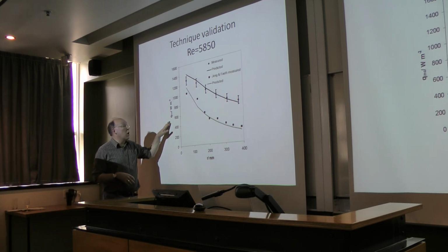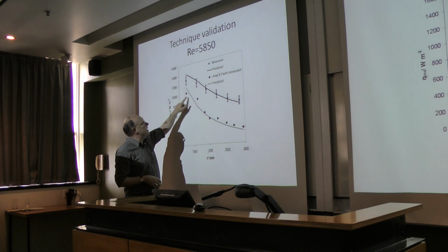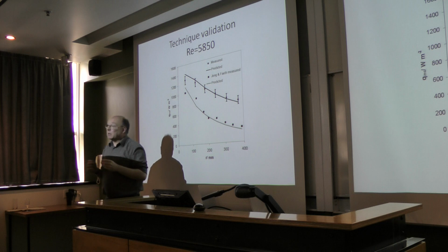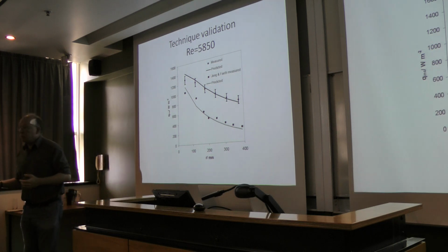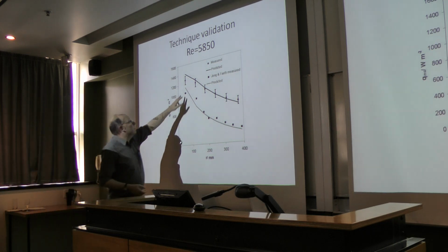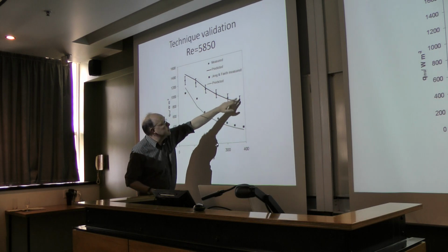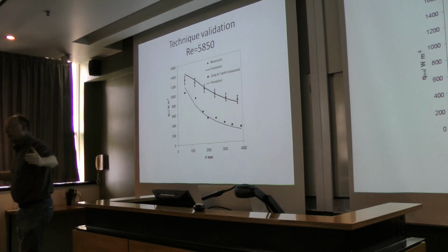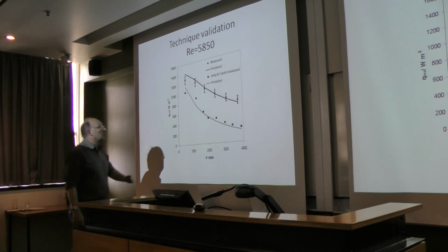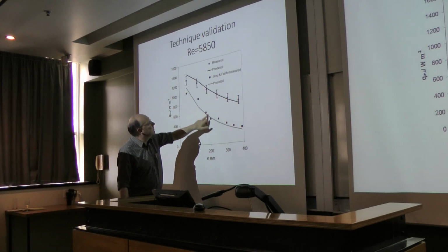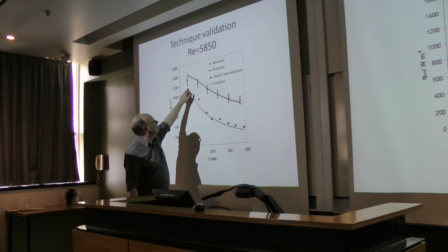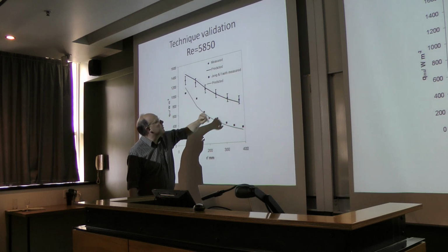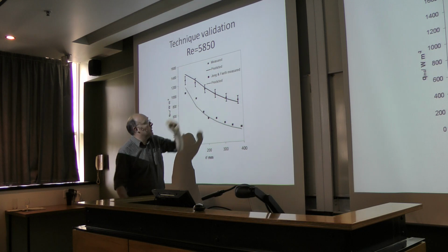What I've got is phase measurements where the spectral window was 1 to 6.5 microns, and I've got my measurements using the thermocouples, which are really taking radiation across the whole spectrum. I predict phase data, and then I have a go at predicting my data with Grosshandler's model, and it's pretty good.